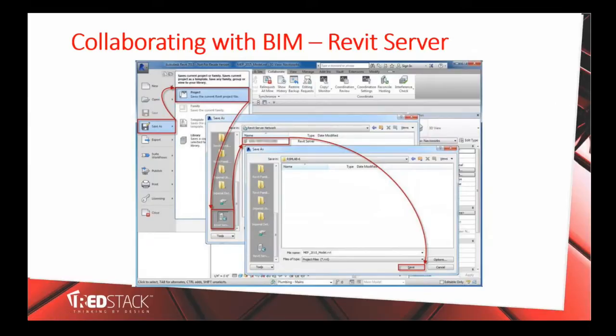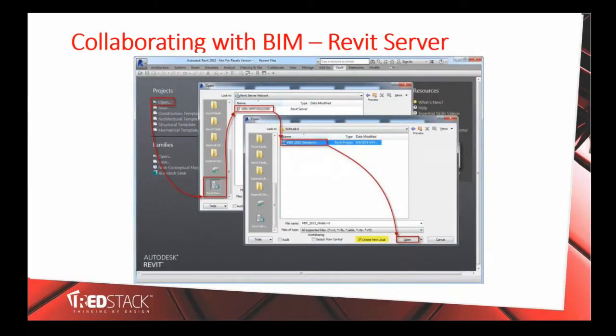So it's not that much of a change, it's just something a little bit different. When you're opening files again, it's slightly different. You would open a project, you select Revit Server on the place list, and then the place list hooks into the Revit Server network. You select your appropriate file, and Revit typically creates a new local file, and then you select open and start working on it as normal.